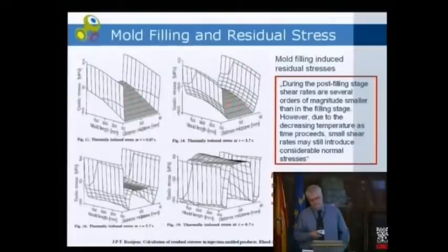Something very interesting, which we just began to consider, was the evolution of residual stresses during the mold filling. This is something which is known for years in case of thermoplastic injection molding. And if you look at such a process, this is the beginning at 0.7 seconds. This is a component, just a plate. Here is the midplane, and we start filling from here to there. And you can see here the evolution of residual stresses during this mold filling process.